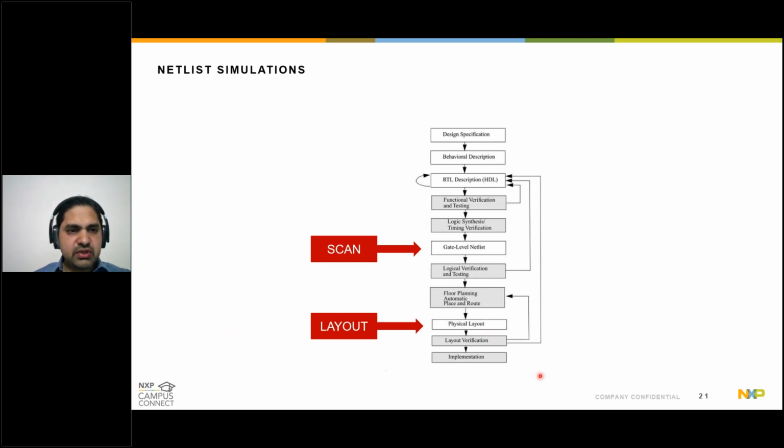The layout netlist is closer to reality and also gives us the capability to run simulations with actual net and component delays for the nets and components present in the netlist, and that we can do using the SDF file. So it is important that we verify the transformed version of the design as well, at least mandatorily the layout netlist, and run simulations with SDF to make sure that there were no issues during synthesis or place and route.